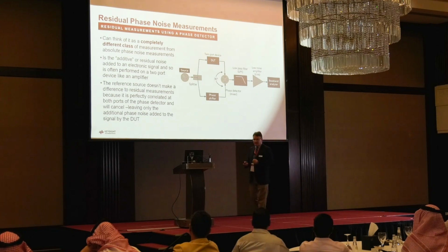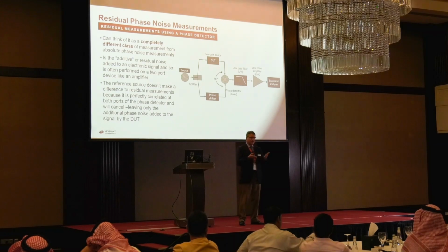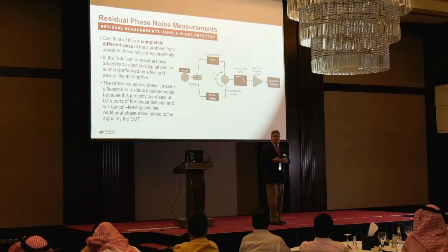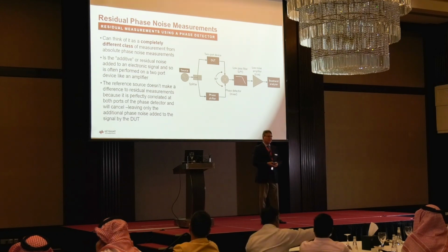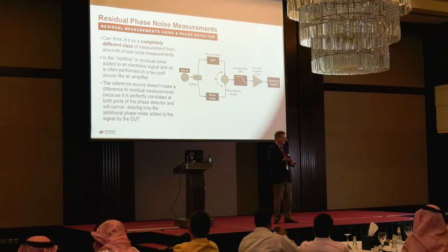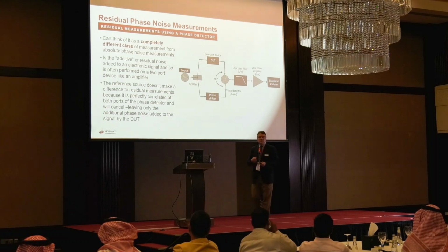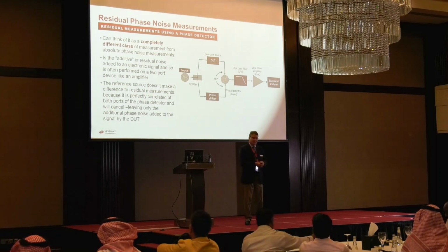So far we've been talking about absolute phase noise measurements. So measuring the absolute phase noise of a carrier signal of interest. There's a second class of measurements that are known as residual phase noise measurements. And in this case, we actually are measuring the phase noise that is added to a signal by a device. It could be an active device like an amplifier, or it could be a passive device like a switch or an RF cable. So residual measurements are done in a slightly different way.